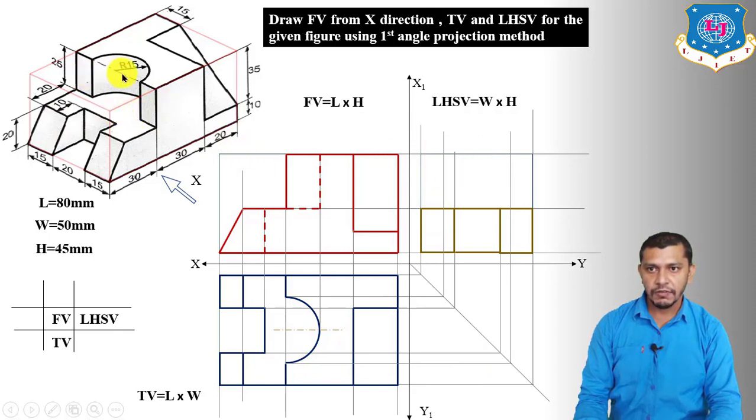So in the left hand side view it will represent three rectangles, one second of this circle and third will be this rectangular part. So draw this rectangle over here, and the remaining part will show us the rectangle of this circular part, or view of this circular part. So this will be the left hand side view of this part and this part.